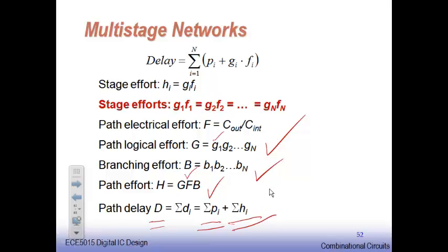Now we are going towards a stage where you have cascades, and in each stage you have complex gates, and all the complex gates have their own logical efforts. For all these stages, what is the total logical effort, and the total path effort, which takes into account the output bigger load to be driven, for example your off-chip bus.